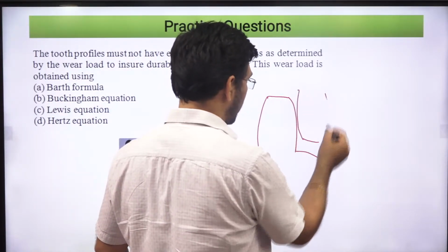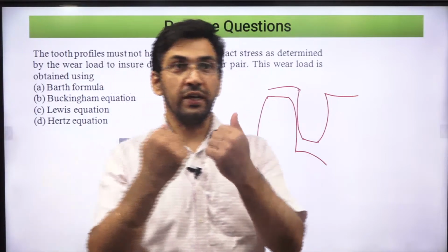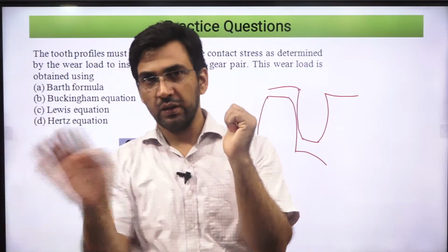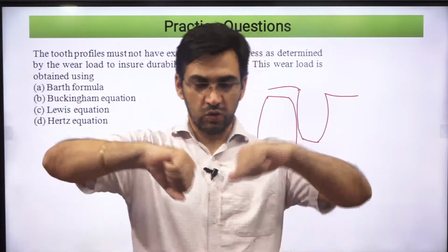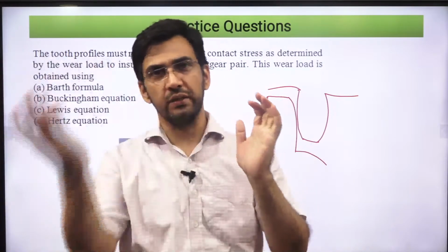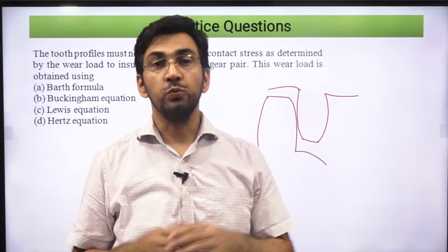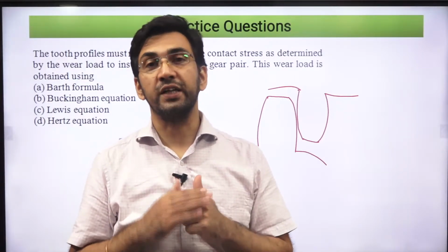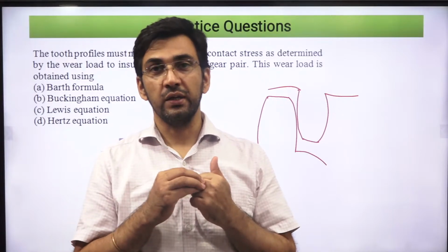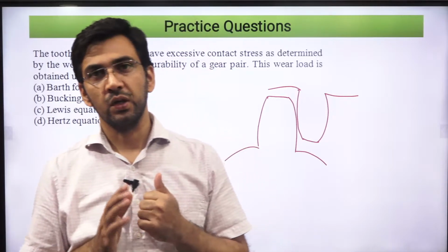Because of the repetitive stresses, two surfaces come, roll, compress, and go back; it goes around, again it comes, compressing, rolling, compressing, going, and that cycle continues. So it is a case of dynamic loading, fatigue loading. Because of that, surface fatigue failure takes place. Cracks will develop on the surface, minute cracks will come out, and pitting failure will take place.